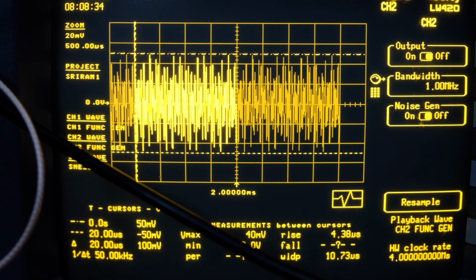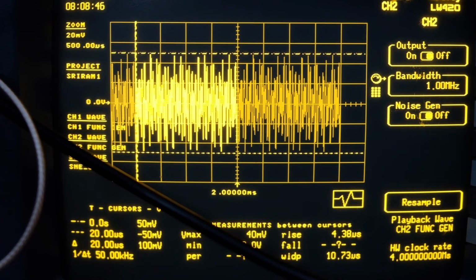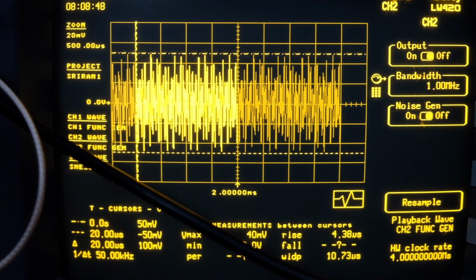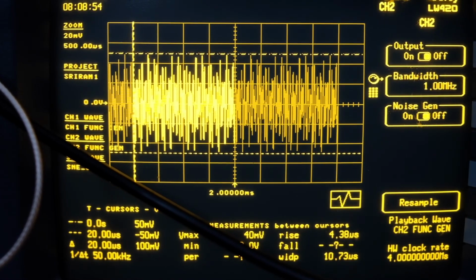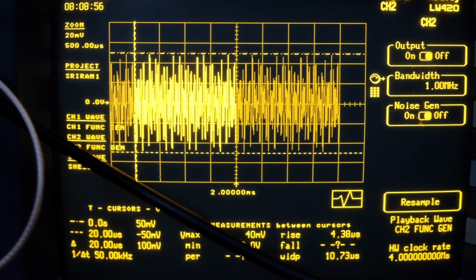The interference signal has multiple components of different frequencies, and it's going to be very large. So this is about 100 millivolts peak to peak, and my signal that I'm trying to measure is still the 550 kilohertz signal, this time at 5 millivolts instead of 50 millivolts. So this is about 20 times larger. Of course, the lock-in can do much better than this, but this is just for demo purposes.